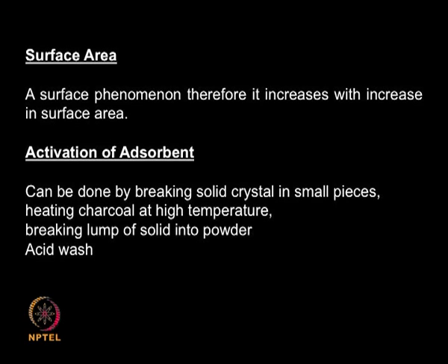Same thing happens in some of the petrochemical processes. When you are passing fuels, you are going to have wax or high molecular weight hydrocarbons deposited on the catalyst surface, and the activity of the catalyst surface goes down. So there the temperature is raised and the tar is completely burnt off, so that the catalyst again gets regenerated. So use of temperature is very good for activating your adsorbent, assuming that temperature does not affect your adsorbent. For example, if you use very high temperature there could be sintering taking place. Sintering is nothing but agglomeration or conglomeration of smaller particles of the surface into larger particles.